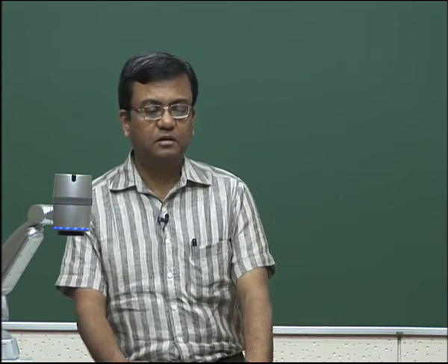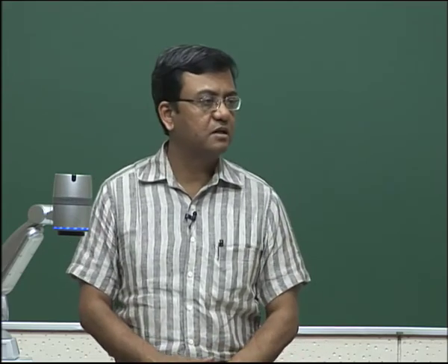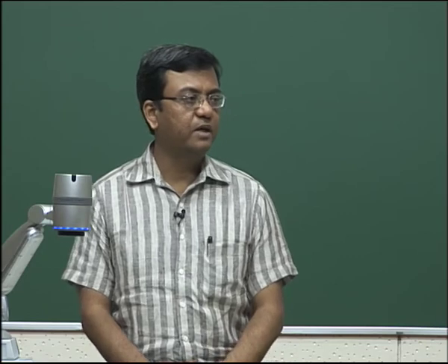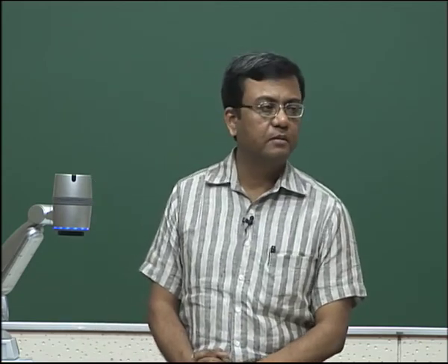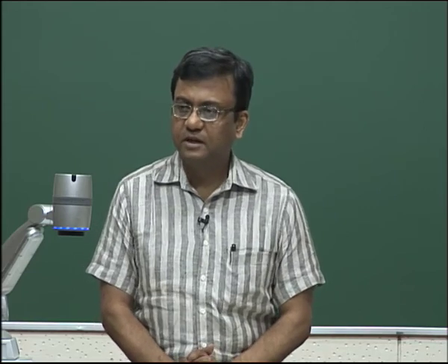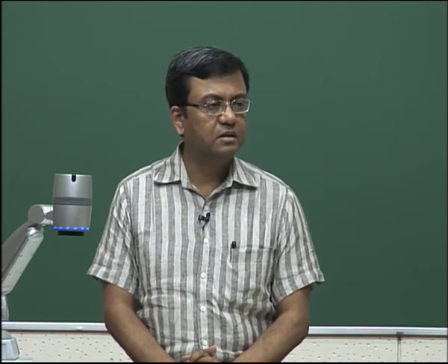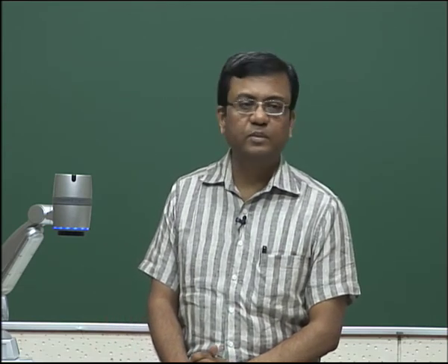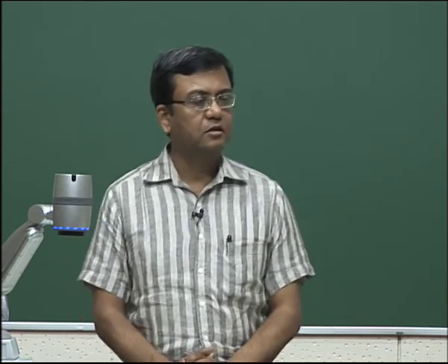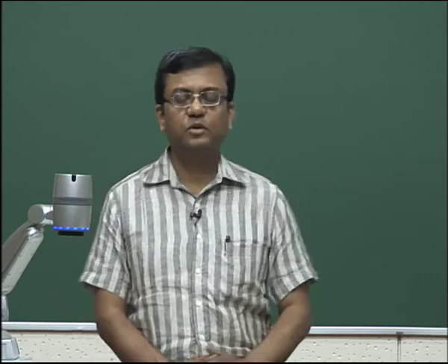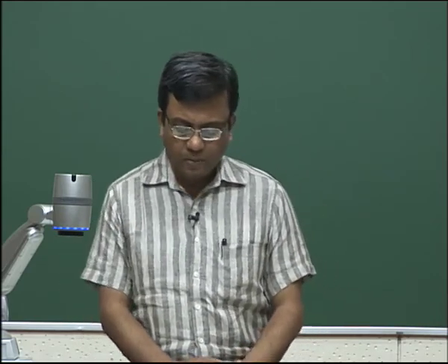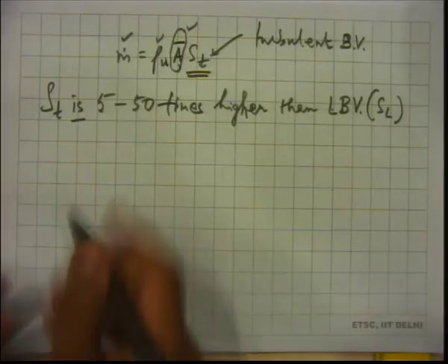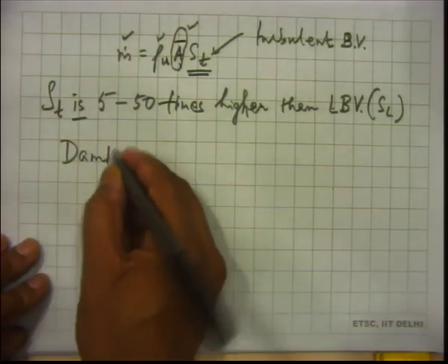and that is because we can understand to some extent now that you have these laminar flames, essentially laminar flamelets, which, because of turbulence, have been made different. The area has changed, they have become wrinkled. So, there is an increase in area, and there will be an increase in burning velocity. So, turbulent burning velocity will be much higher than laminar burning velocity. So, people tried to calculate this, and one of the first models for this calculation was given by Damköhler himself.